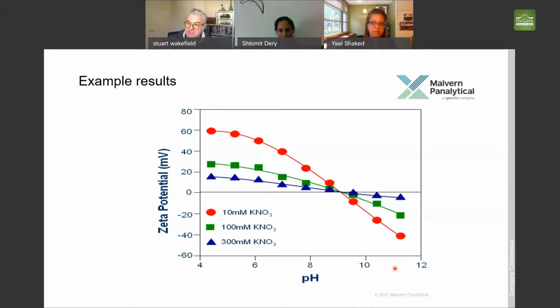But of course, you can see if I have a different amount of chemical, in this case 100 millimolar, we have a very, very different profile. So it's a balance of formulation between the right amount of chemical at the right pHs to give us the Zeta potential numbers that we want. And remember, we want to be somewhere in this area for a Zeta potential measurement of water for optimum flocculation.